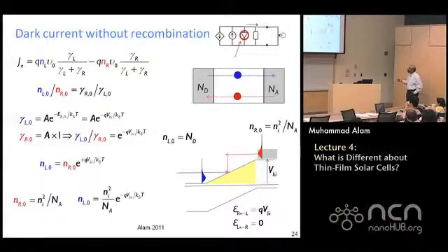Okay, so by the way, if you have this gamma L and gamma R, put it in this equation, that will tell you this concentration on the left hand side, how is it related to the concentration on the right hand side. Now, do you remember what this relationship is? This just turns out to be the law of the junction, essentially telling you that two sides, the electron concentration, are exponentially off and equal to this VBI, or whatever the barrier height is.